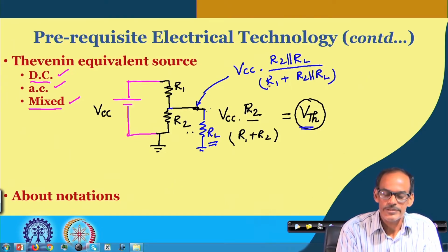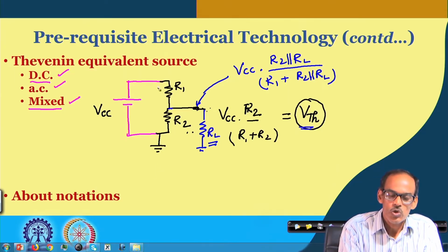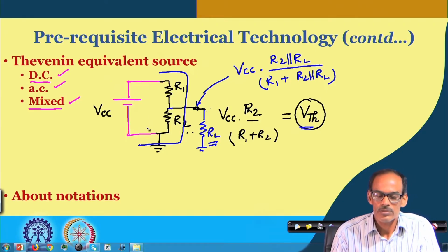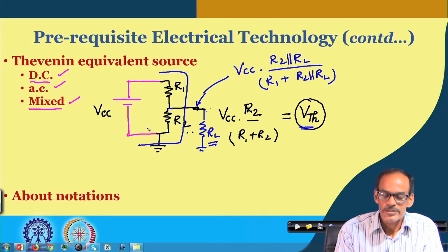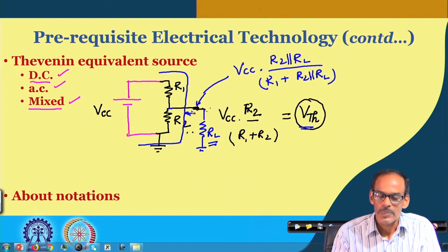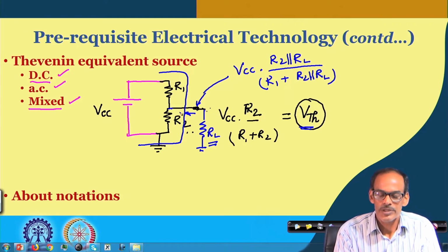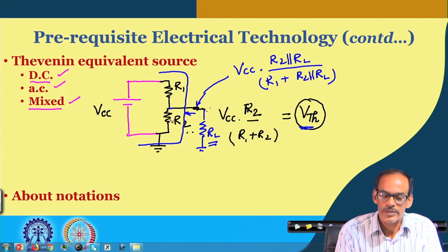But in general, this circuit may be fairly complex, it may be nonlinear and so on. So, if this portion is not really visible to you, then how will you analyze it? Of course, without any information it will be difficult, but if we characterize this circuit by looking into this port from outside, as the load is seeing this circuit, then along with this Thevenin equivalent voltage and something called the Thevenin equivalent resistance, you can model this circuit and handle even a fairly complex situation.